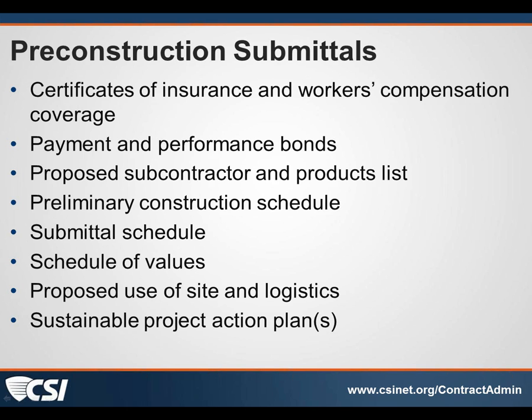It can be used as a tool for us in helping to plan out our work, to know when submittals are going to come in, what staffing we need to have on board to review them when they arrive. The other thing that I have used it for, and it becomes a tool for, is to help ward off delay claims. If the contractor is not adhering to his submittal schedules and his submittals are late, then that in and of itself is a delay. If the submittal was supposed to be in on January 1st and the submittal doesn't get in until February 1st per his submittal schedule, he's 30 days behind on that submittal schedule.